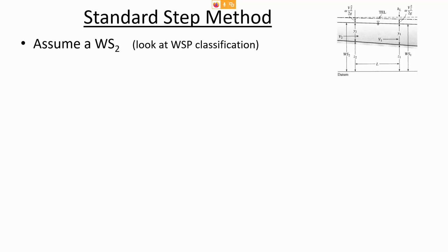First of all, here's the procedure. We're going to have knowns. We'll know the depth at 1, and we're trying to figure out what the depth at 2 is. And so we have to start with a guess. And we've done that a lot this semester. I think you'll remember many different procedures where we didn't exactly know, for example, what the amount of head at the junction of 3 pipes was when we did the 3 reservoirs method.